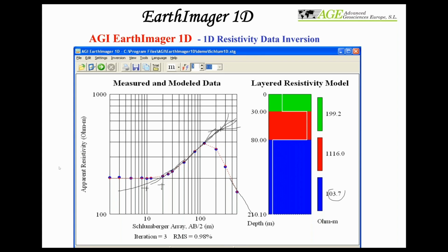Another thing is he's asking how many electrodes are needed. I lost his other question. Okay, how many electrodes? I think if the question is related to contact resistance, again you can put many different electrodes in the same location to increase the surface area and then reduce the contact resistance.